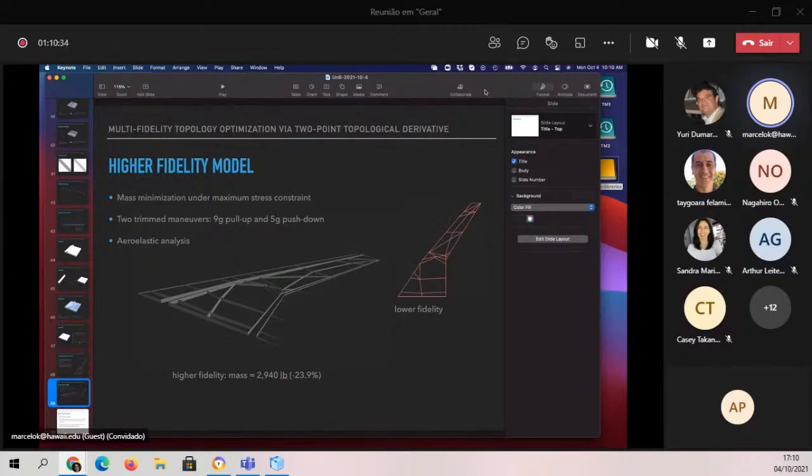So it's very fast. I compared the barycentric against the usual moving meshing techniques that you use in ALE, right? Because your problem, I'm sure you're using an ALE method, or there is one way at least that you can use an ALE method to track the boundary and move the mesh. And so the usual techniques for tracking the mesh or moving the mesh in ALE, like the Winslow, right, or the Laplace or the elasticity, I programmed them and compared them. They are just too expensive, as you mentioned, even to move the mesh.